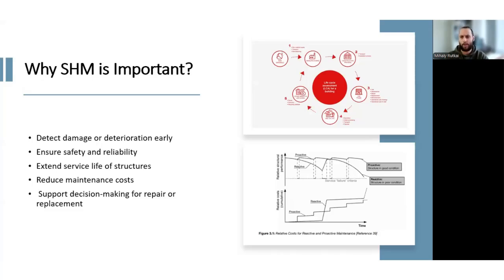The reactive approach is where you let the structure sit and do standard maintenance until an issue arises, then address the issue, and then continue on with a likely now updated maintenance schedule. This then repeats until the end of a structure's life cycle, usually. The issue with this approach is that over time, the structure is left in a much worse off state, and it is much more expensive to do repairs this way.